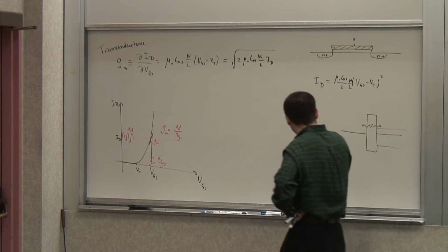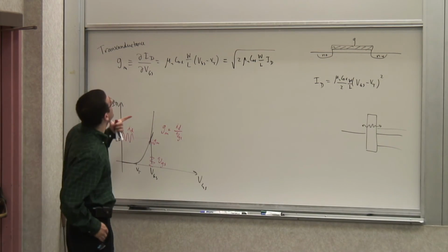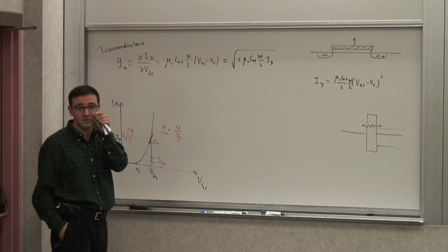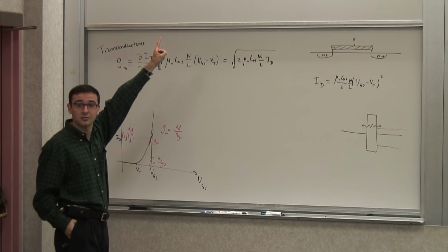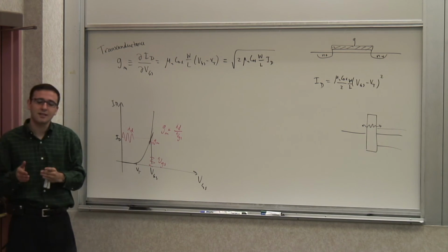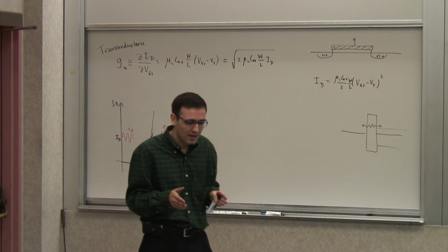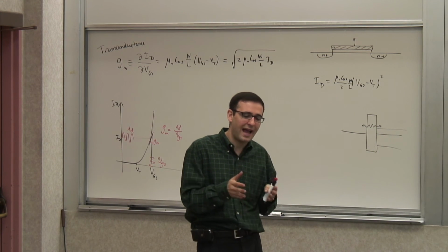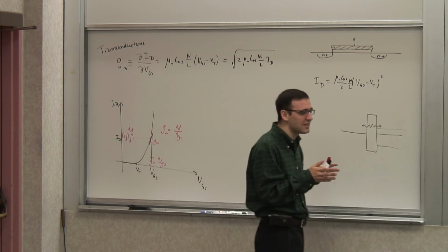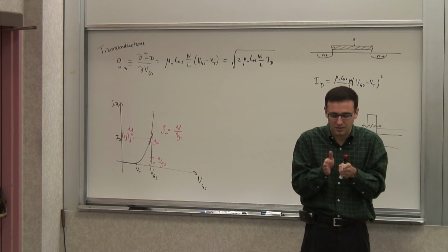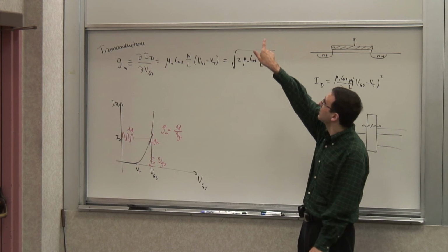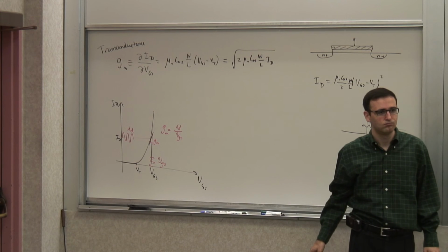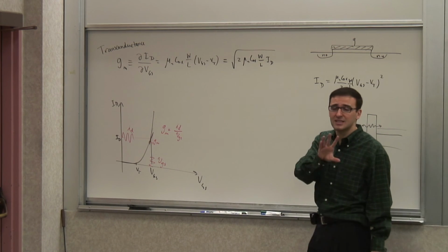So you can see these are real effects, and because of that, nowadays, if you really want to model a really short channel device, like a 45 nanometer or 65 nanometer channel transistor, you have to put a resistor there to account for that. Then you can do that. But for most of the circuits we are designing, and most analog circuits, that's not a problem. We don't use 65 or 45 nanometers often for analog circuits, and the current flowing through one or two of them is not very significant. We're not using a whole lot of transistors. But you have to be aware of this, and this can become a limiting factor even in certain analog cases.